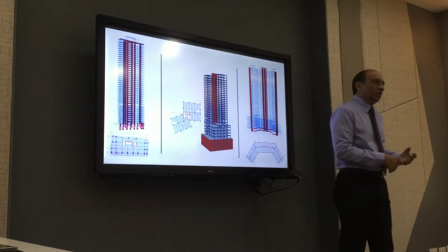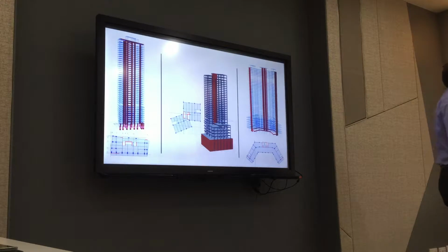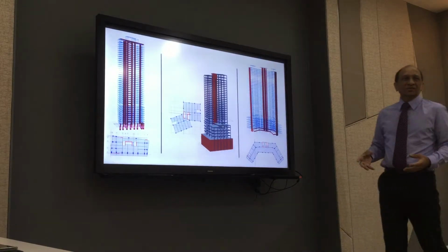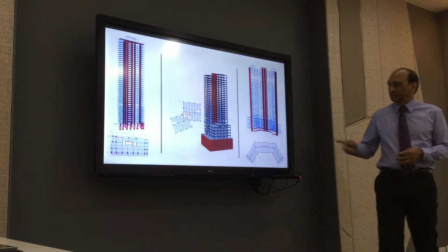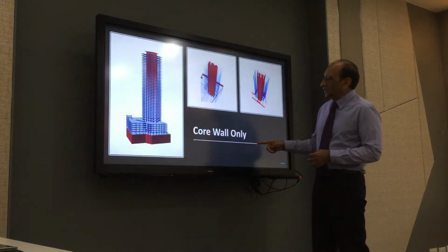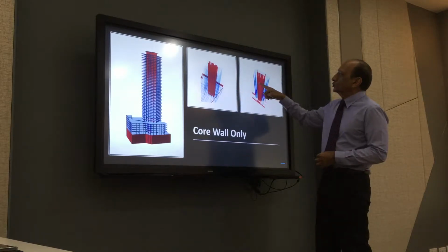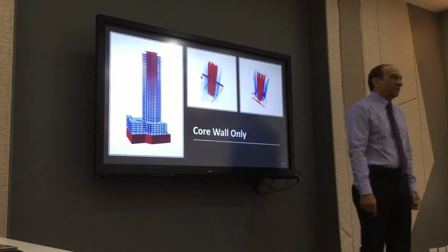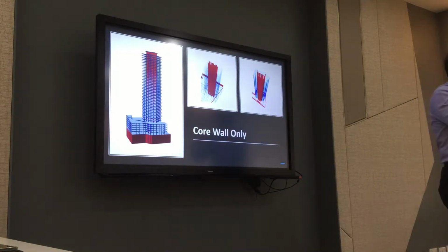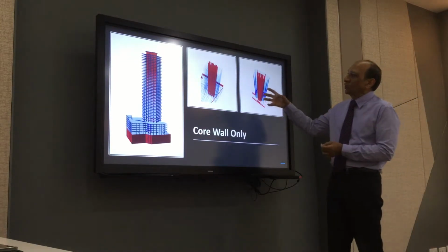So people have so many ideas on how to make a structural system. Walls only, coupled walls, distributed walls, core wall plus column, endless configurations can be created. Pure core wall, no other element. Flat slab and core wall, very common these days. A lot of people want to do that. Just construct a core wall and columns and flat slab, no beams, no interaction between them. So this is also possible up to a certain height if the core wall is big enough.